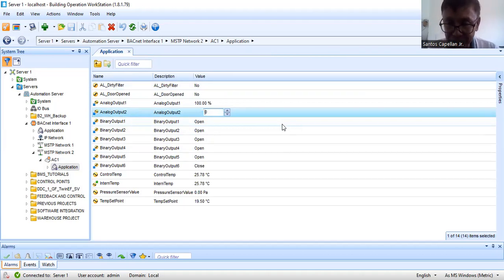coolers. Now, as a BMS engineer, you need to specify exactly what your requirement in the field is, so that when you order this, you have to tell them. Maybe you can show them your graphics. Then you tell them that you want these values, or the default values, for this information displayed in your graphics. Then they can reconfigure the thermostat before delivering it to the site. Or maybe they will give you the capability of reconfiguring their thermostat if they don't want to send someone to the site to do it for you.